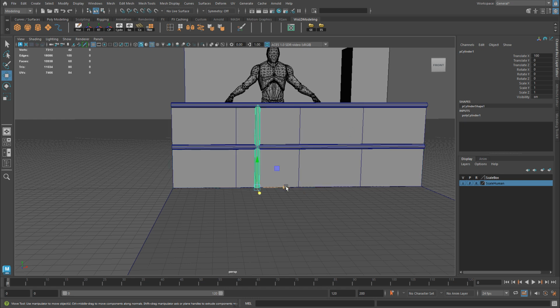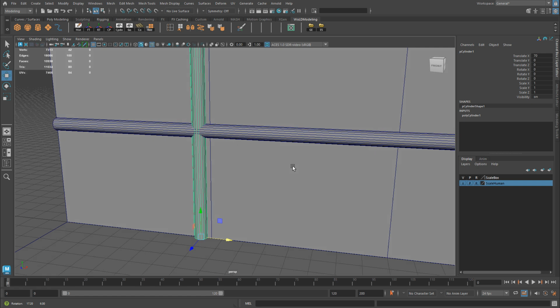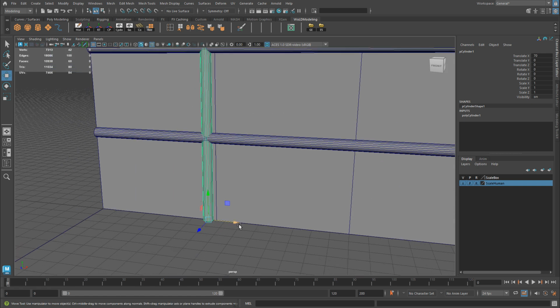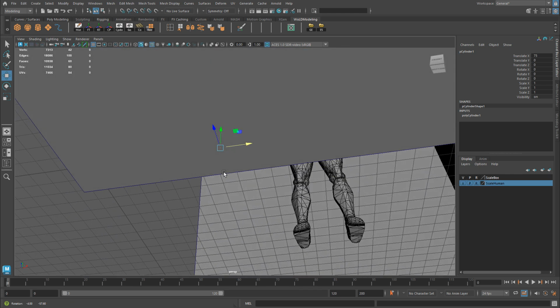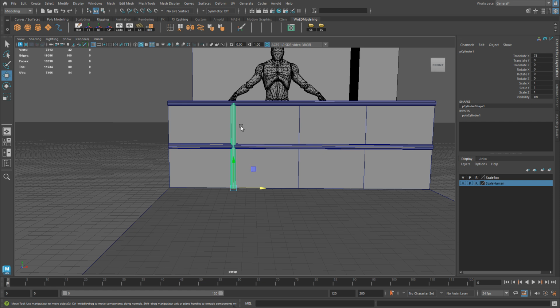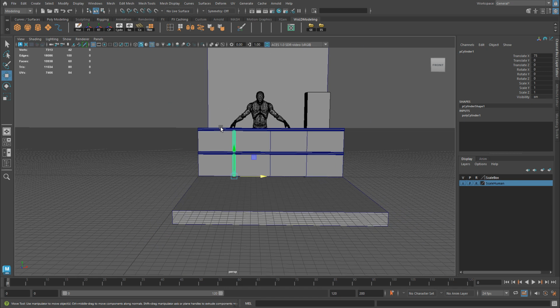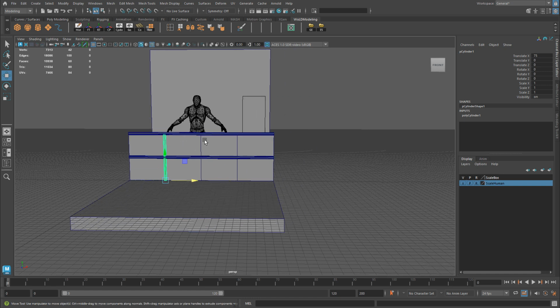So if I take this piece and snap it to the grid, or I can actually snap it to this line, to the edge right here, by activating the Z-axis, so it's yellow, left clicking on it, and then pressing C and the middle mouse click and drag on this edge, it'll snap to the center at its pivot point. So this is where I want to keep this railing, because I want to make sure that these are equal distance from each other, so when I duplicate the entire railing piece and continue the 300 piece across, everything will be even and exactly the same.